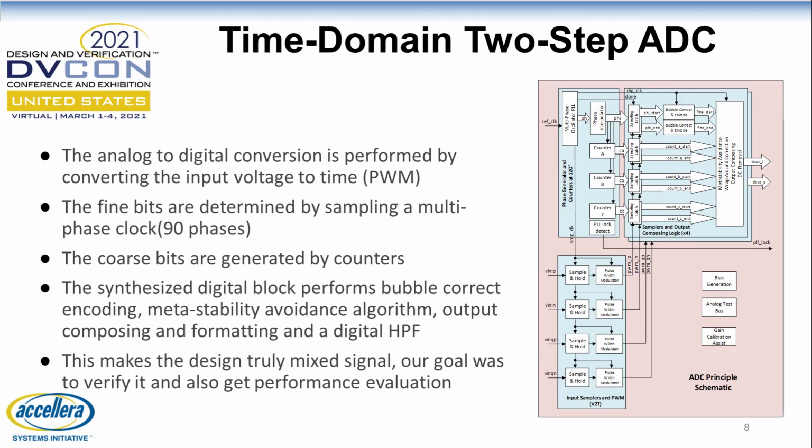We use a set of 3 counters fed by clock phases of 120 degrees offset that help us to avoid or at least severely reduce metastability rate by choosing the counter that is least likely to go metastable.